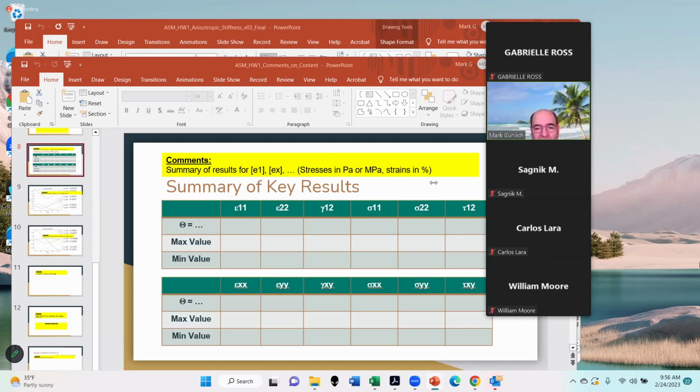What do you mean by strain? It's a very good question. What do you mean by strain in percentage? For strain, it's quite normal to discuss it in percentage. For example, people like myself, you tell me strains are 0.5% or 0.1% or 1%, and it has huge meaning, because I know if it's close to 1%, it's bad. It's already close to damage.